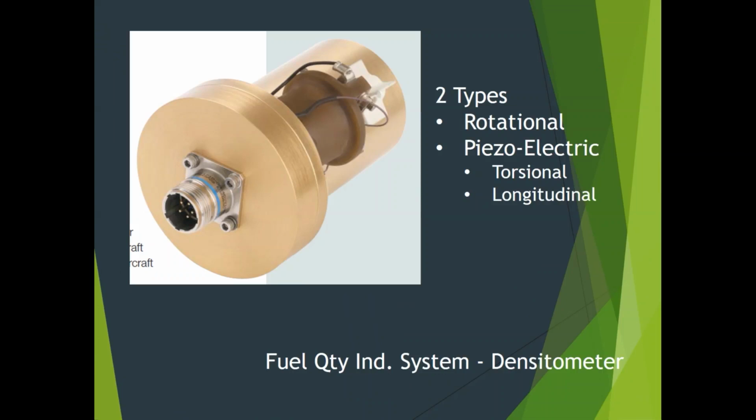So these use vibration to do that. So torsional produces a twisting motion. It's almost that same paddle wheel, but instead of spinning, now it's vibrating like this. It's kind of back, forth, back, forth, back, forth. And same thing. So now it has a known vibration. We send a known frequency into it. It's rocking back and forth at a certain speed. The thicker fluid is going to slow down that vibration, right?